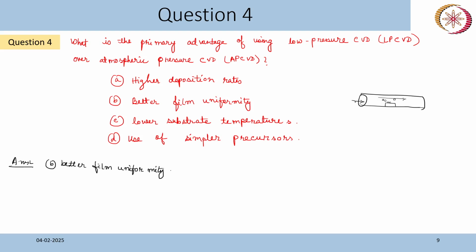with a carrier gas. So normally how we introduce these reactants or the precursor, we normally use argon gas, which is a noble gas. It will not react, and that is the carrier gas in case of CVD. So the carrier gas and the reactants will flow, and the chemical reaction will happen, and whatever byproduct comes from the chemical reaction will be carried away by the carrier gas out of the system. Okay, so finally we'll get a substrate with a thin film.